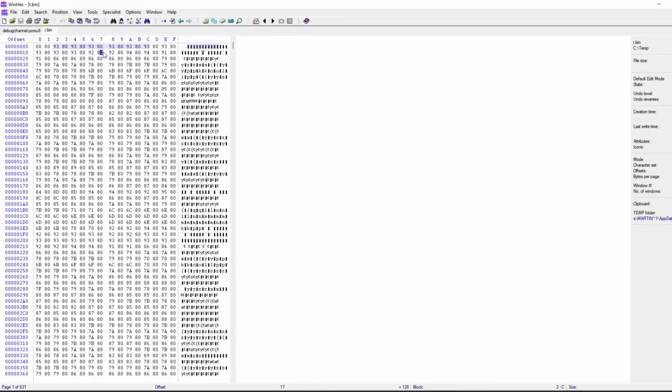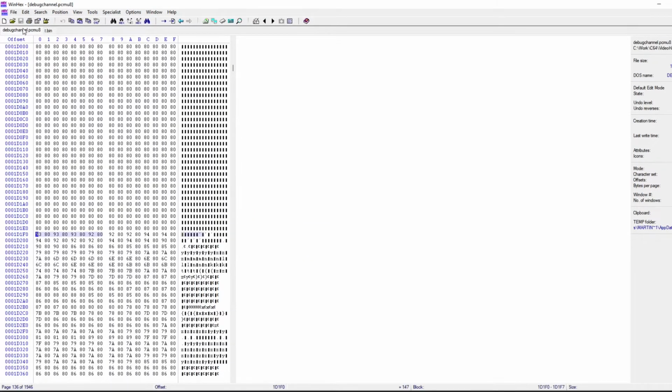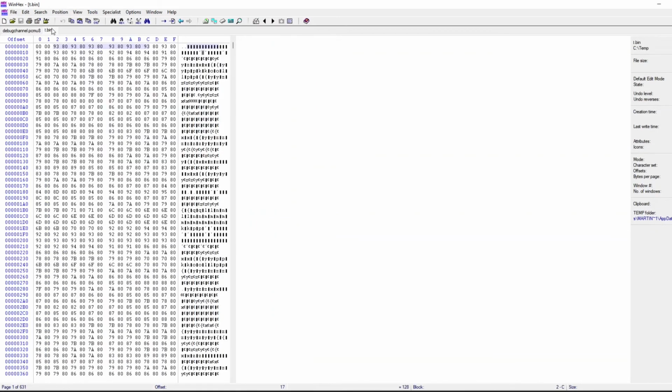Now, the register updates compared with the emulation and the timing of those register updates is not precisely in sync with the hardware simulation register updates. Okay, so we're not going to be getting completely the same values in lockstep. They're not going to be precisely the same because the register updates are occurring at different real-time simulated time positions. But what we should get is that we should start seeing values that we expect in approximately the correct ranges.